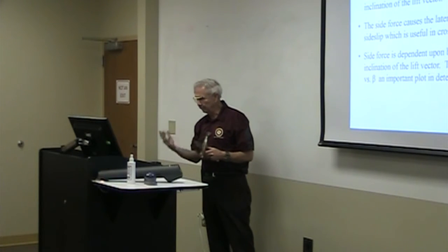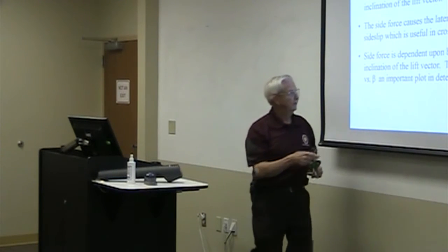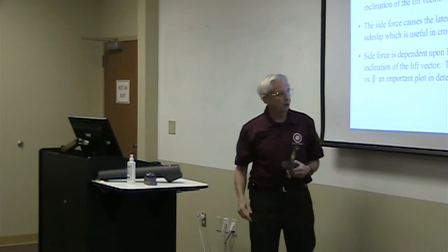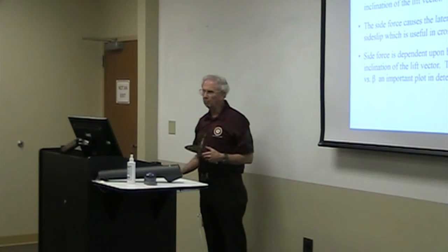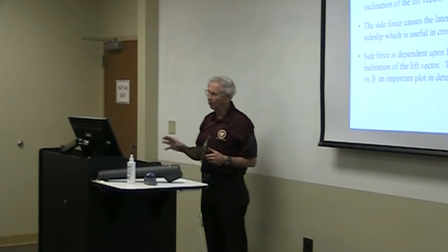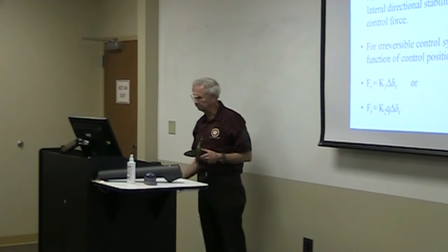It's dependent upon bank angle due to the inclination, and that makes a plot of bank angle versus side slip an important factor in determining side force. And if you remember back to the equations I had on the board, that term was in the equations for a steady heading side slip.